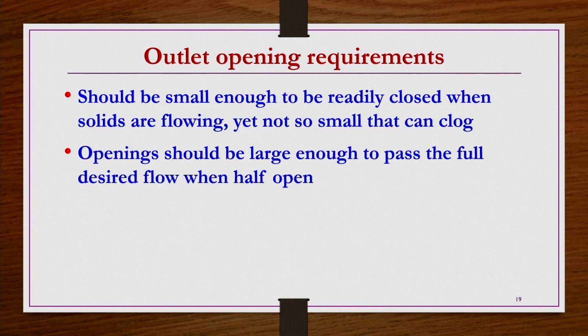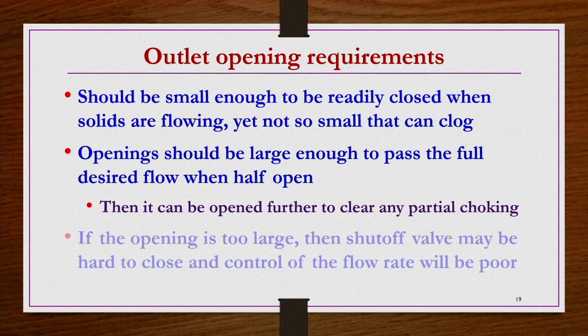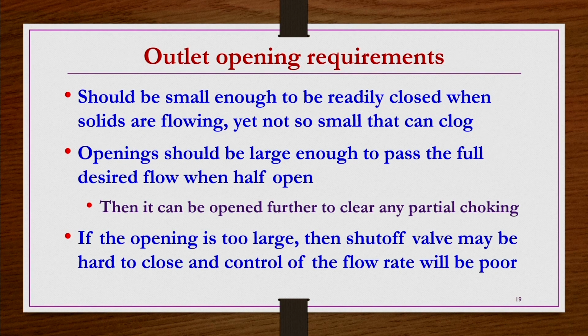Even if it is only half open, not completely open, you must have the desired flow rate. So, that is the opening requirement, and then it can be opened further to clear any partial choking if there is any. But if the opening is too large, then a shut off wall may not be possible.